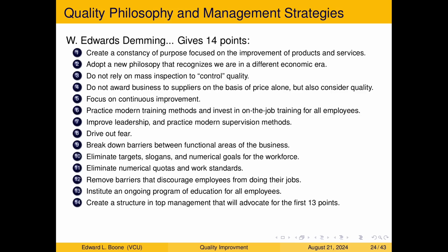Is what it's saying. Do not rely on mass inspection for quality control. This means I have to look at every single item that leaves. No, you want to use sampling. You want to use statistical techniques so that you don't have to spend a lot of money and time trying to control quality or to avoid a bad part leaving. You produce processes that don't produce bad parts very often.